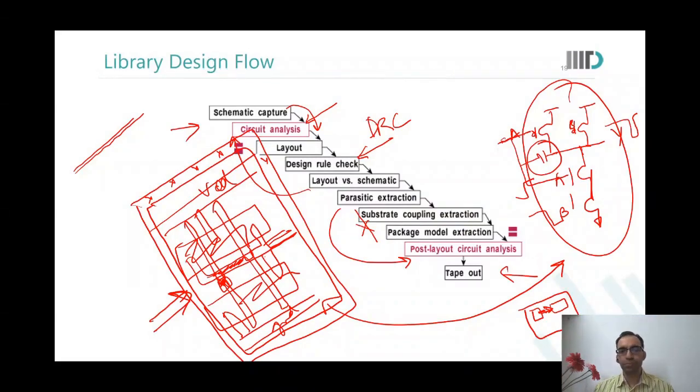There is another technique which we call deep n-well or triple well technology. We will not look into that just yet, but there are many methods. At a designer level, you can work with either triple wells or with guard rings. Guard rings are more appropriate when you do not want to lose area. When these circuits have to be placed really close together, then guard rings are denser.